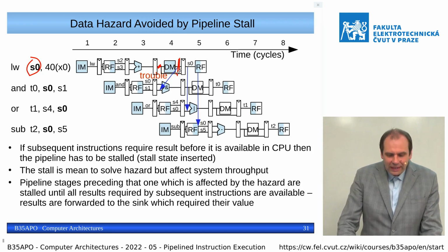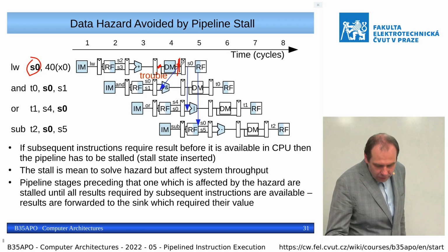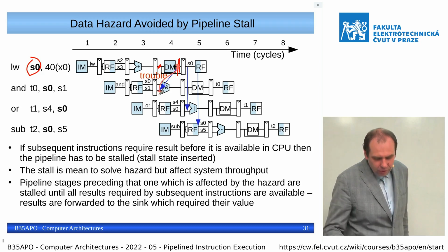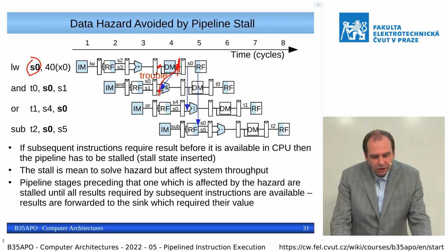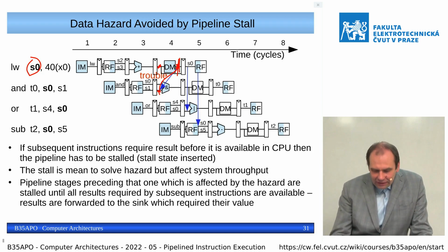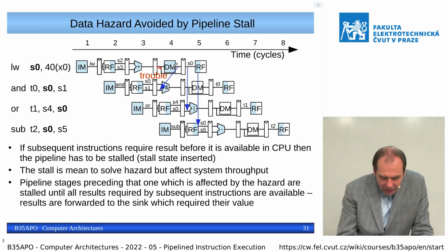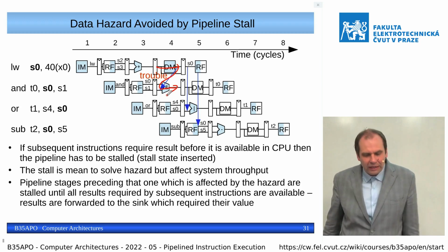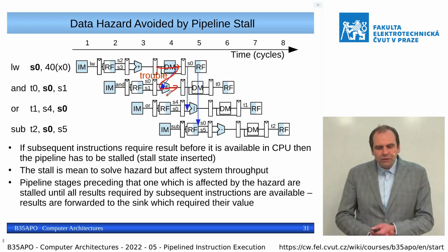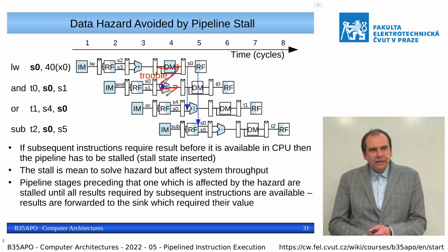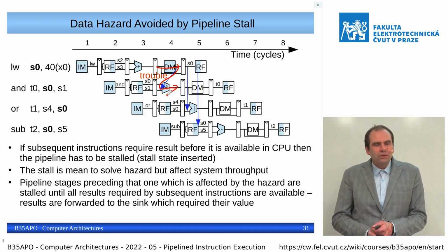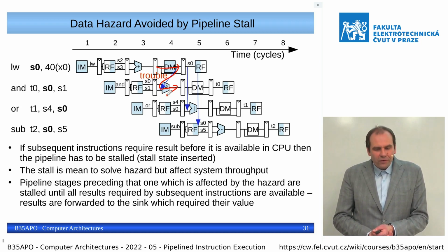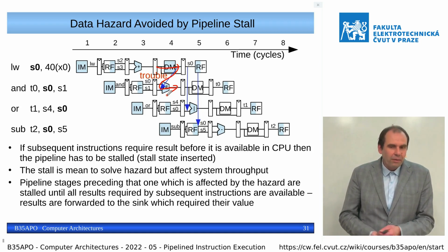So in this case, we can forward the value from this location to the input of the arithmetic logic unit, for sure. But in fact, we need time to access the value in the memory and then process it through the arithmetic logic unit. So if we do this kind of forwarding, then we need to lower the clock frequency almost by 1/2, or by 2.